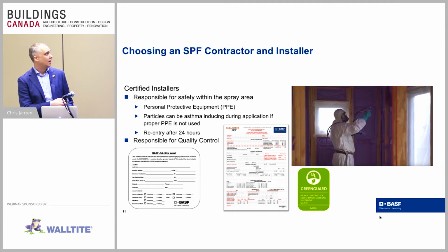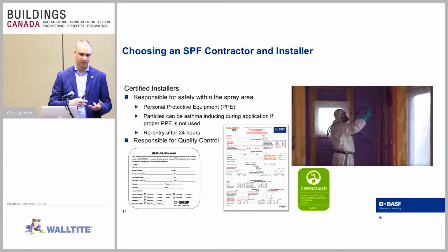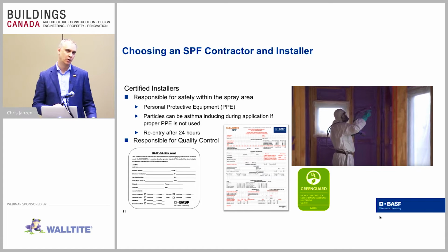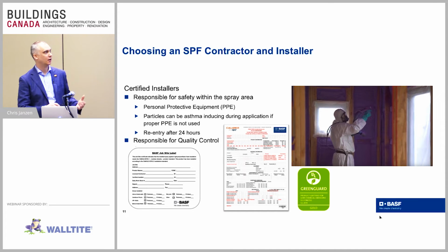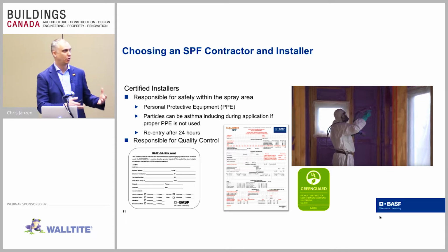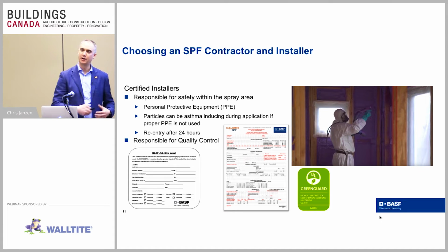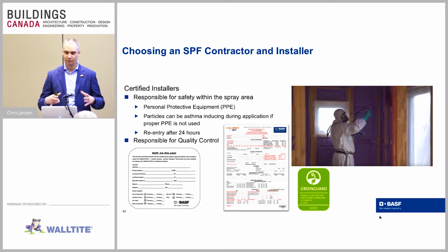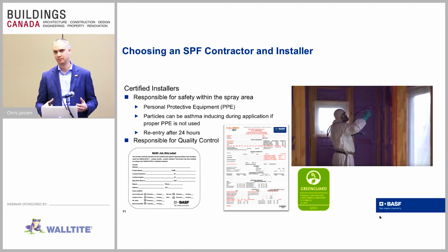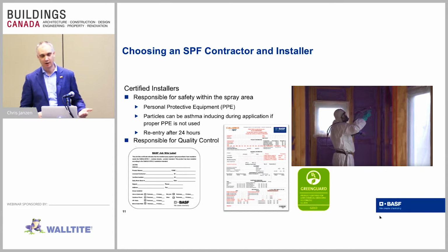And then the installers at the end of the job, they'll leave what's called a job site label behind, which is basically the name of the installer, company's name, date that the product was installed, what the R value was, what product was installed, and where it was installed. And all this helps as supporting documentation, as a lot of manufacturers will have GreenGuard Gold certification. That's basically making sure that the foam is classified as a low emission building material. So GreenGuard Gold means it's safe for sensitive individuals, like in schools, in hospitals, that kind of place.